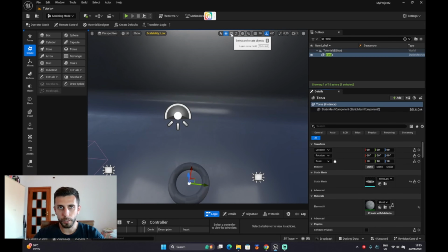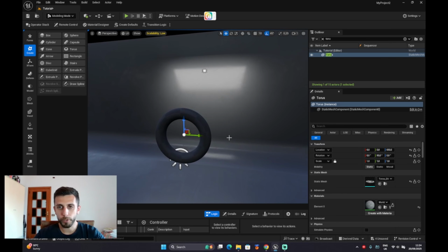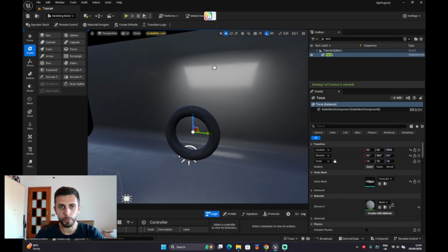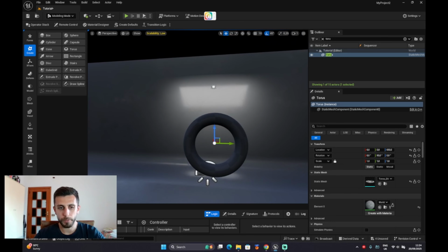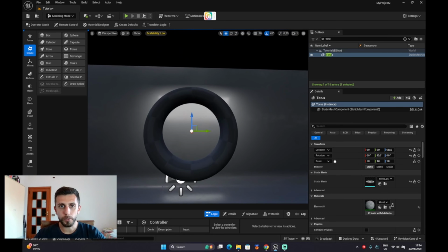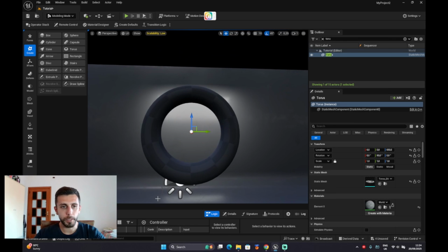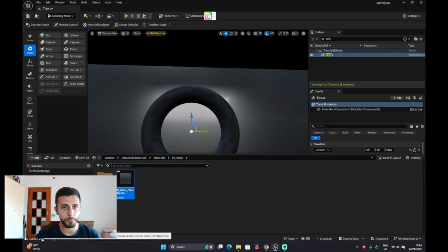Then I'm going to turn it 90 degrees. Make sure that snapping is on, so it's easier. 90, and then I'm going to move it up on the z-axis 650, and we're going to use this 650 value to align all the elements that we add to the scene, so it's easier. Okay, now this is going to be our pipe, and the next thing we have to do to make things a little easier is to start assigning the materials.